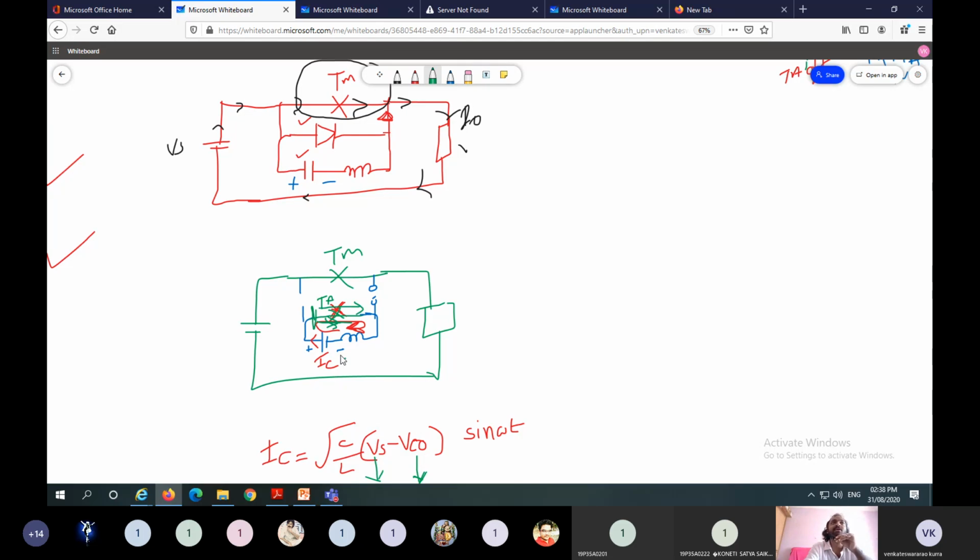It is reversed for the capacitor only, because in the previous state the current is from left to right. Compared with the previous state, the present state current is reversed, so the capacitor current is taken as negative. But for the auxiliary thyristor, the current flows in the forward direction, and the thyristor always allows unidirectional current, so it will be positive.